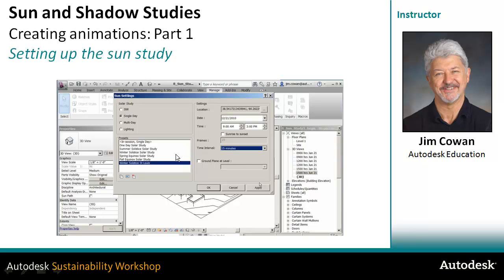And the way that you do that is to save the name of the settings, and then for a particular view, tell it which Solar Study is applied to the view itself. Now, I've used the naming convention of saying Winter Solstice St. Louis, but in fact, it's the location of the project that's always used. So you really don't need to put St. Louis in there. It was simply a naming convention.